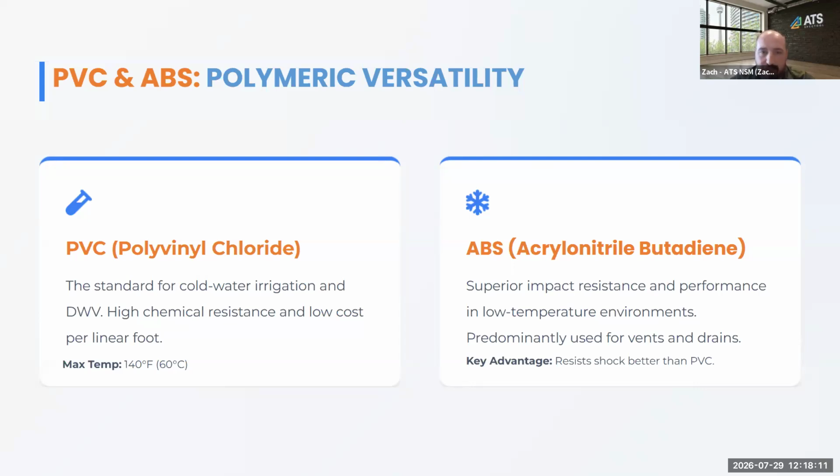And in some cases, depending on the standard rating, different versions of PVC, different versions of ABS are going to meet different standard ratings. If they have the NSF certification, then you can use it for potable water. But really, it's going to come down to each individual line for each of these products. So just look for those codes and standards is probably the most important piece.